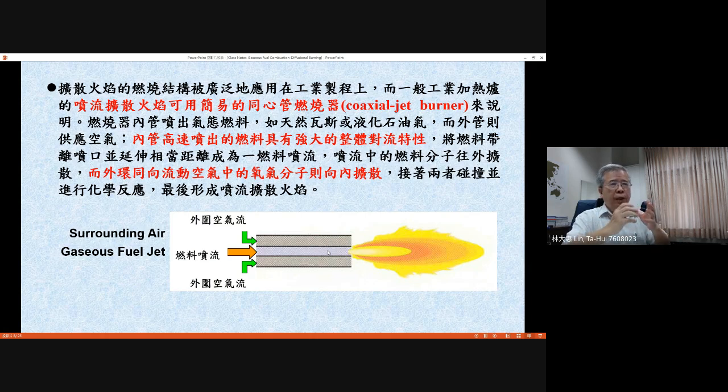The fuel supply for a candle flame basically comes in from the center wick, right? The liquid wax will evaporate and diffuse from the center wick to the surroundings. This evaporation rate is relatively small and cannot compare with the momentum of a fuel jet coming out from the burner, induced by the pressure gradient, because the fuel can be injected to a longer distance.